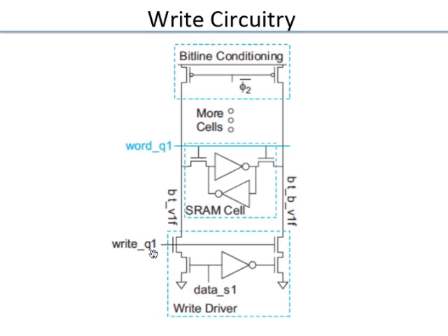Now, what is done out here is, either you can have a complete NAND gate, then the pulling up happens completely from the NAND gate, or the pull up is done through this precharge. It's the same: you precharge, then you pull down one or the other side with the data. So what all this does is it adds to the timing control. You have to generate these signals which control all these different things. You have a small circuitry which is generating all these timing signals.